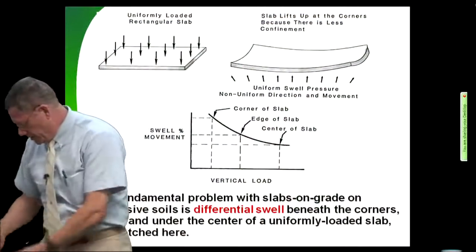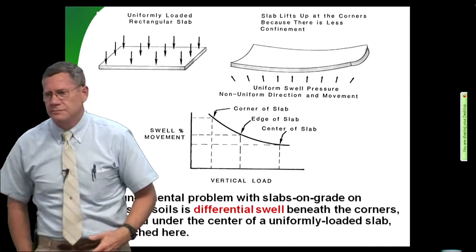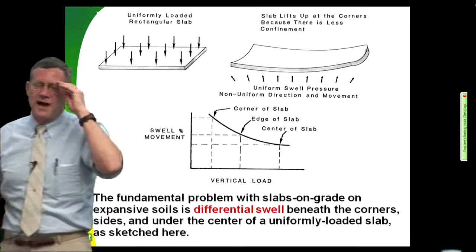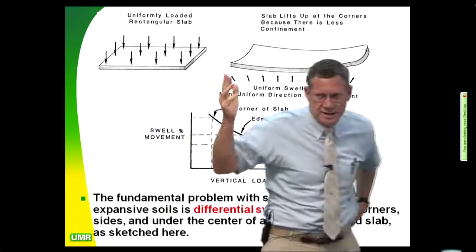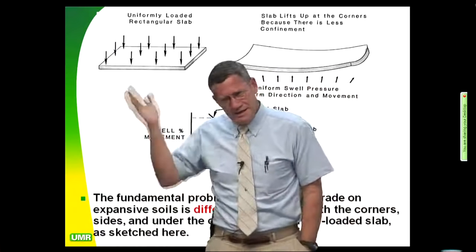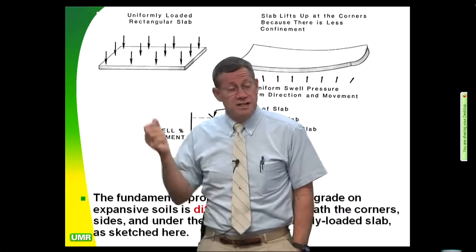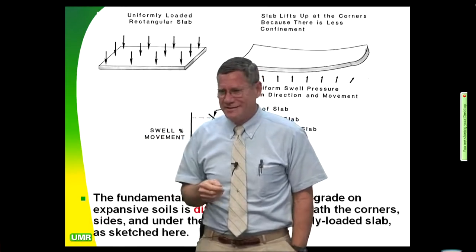Now, if we had the basement of a hospital, what do they keep in hospitals? Well, yeah, morgue too. Yeah, the morgues don't weigh too much. No, file cabinets. What do you think file cabinet bearing is? Want to hazard a guess? 10 times higher, about 300 pounds per square foot. So that's the biggest load you design for until you do a paint factory.